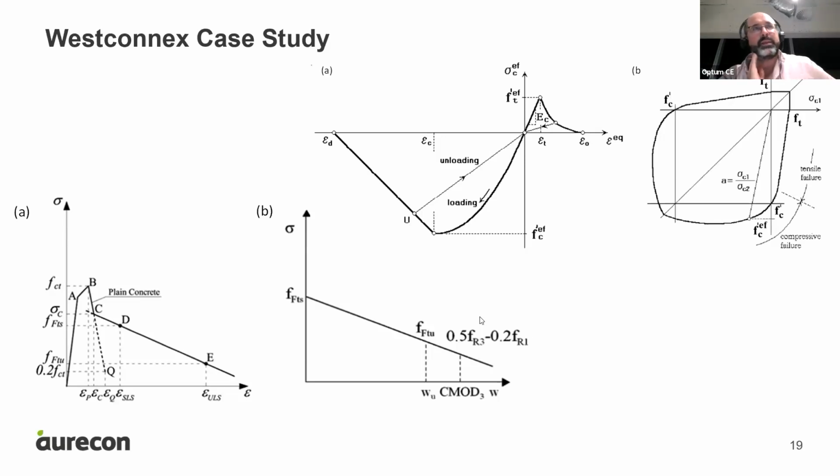It's hard to get much below those numbers because then you start losing the fiber network. You need a certain amount of fiber so that once a crack develops, you can be confident that you have fibers available to cross those cracks. But 30 to 35 has been a number that has been very successful here. For shotcrete, more in the order of 35. For segments, we are going in the 30s.